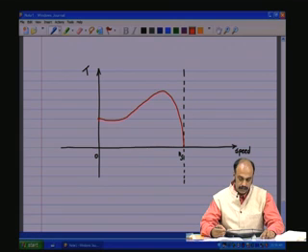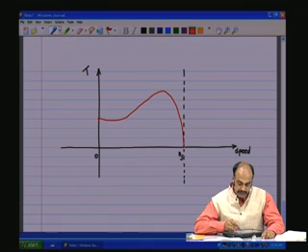If you look at this point, you see the torque is 0 when the motor speed or the shaft speed is at synchronism with the rotating magnetic field, because there is no relative speed between the rotor conductors and the rotating magnetic field.